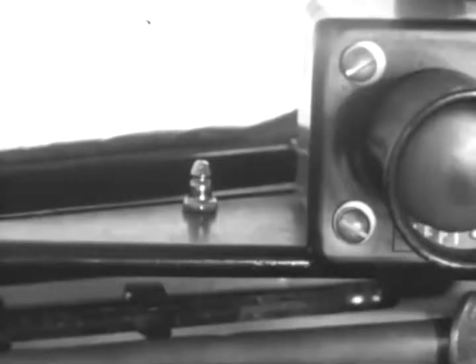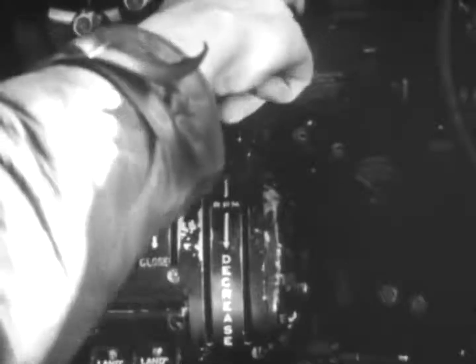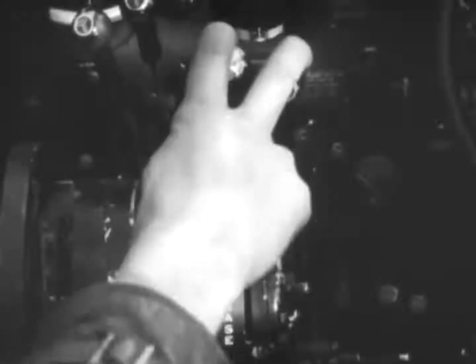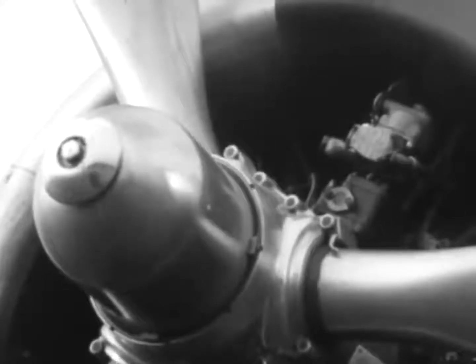This propeller is capable of feathering in flight, and in addition has the constant speed advantages and the high pitch range of the Hamilton Standard constant speed propellers, counterweight type. The hydromatic propeller can be identified by its large oil dome with nut or breather cap on the end and by its governor on the nose of the crankcase section.